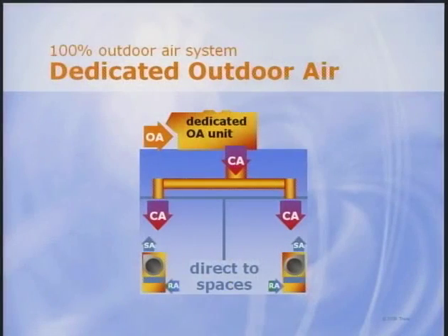It seems that a lot of designers these days want to decouple the latent load from the sensible load using a dedicated outdoor air unit in a 100% outdoor air system. One air handler dehumidifies all of the outdoor air while local units handle the sensible load in each zone. If the outdoor air delivered to each zone is dry enough, it prevents high zone humidity.